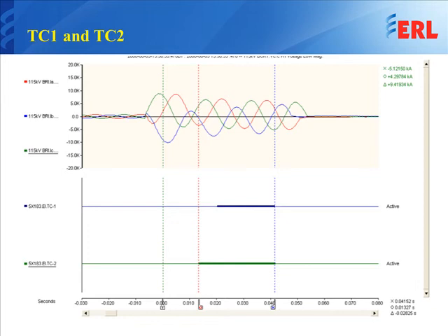So what we got here is an operation on a 115 kV system, and we have two trip coil surge detectors. Now, trip coil 1 and trip coil 2 operated, but trip coil 1 operated with some time delay, and that could be due to the way that certain signal got there. So this needs to be investigated.